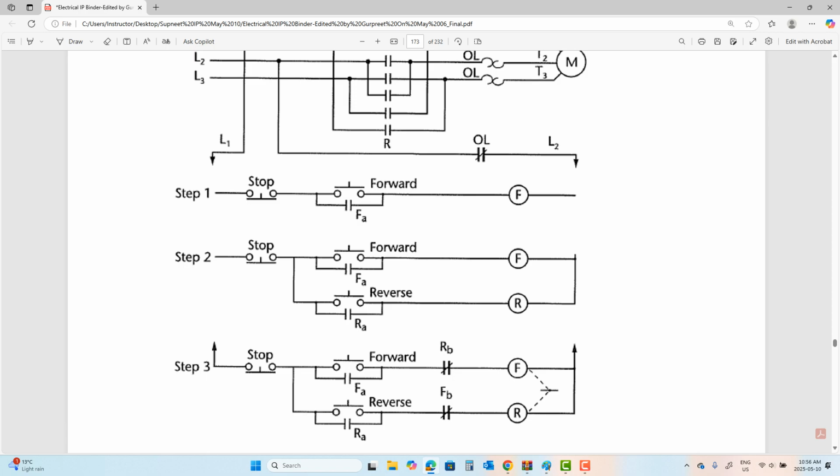If they are not interlocked, it can kill the dynamics of the motor or the whole mechanism of the motor, which will actually burn the motor. Okay? So you end up shorting it. Say that again. You could possibly end up shorting it. True. That's why this dotted line that you see on the schematic shows it's mechanically interlocked.